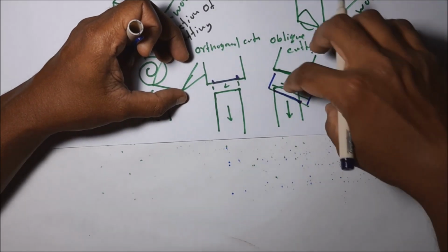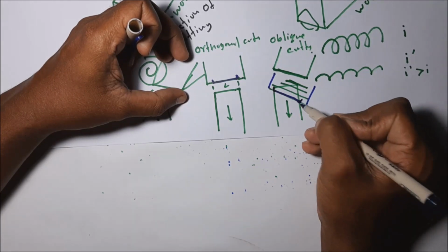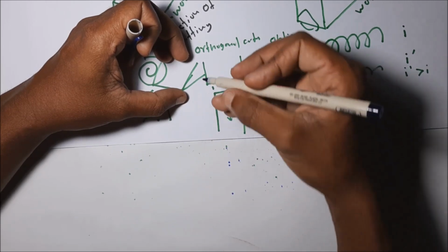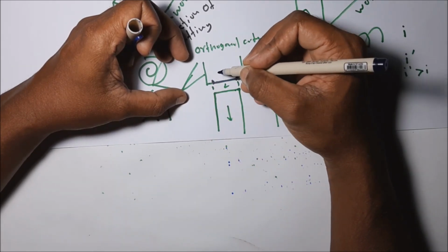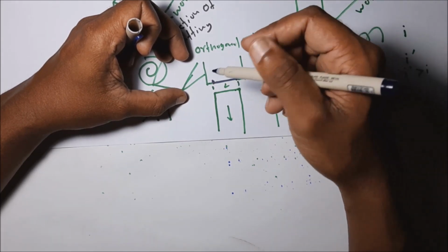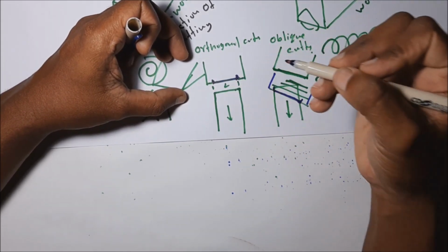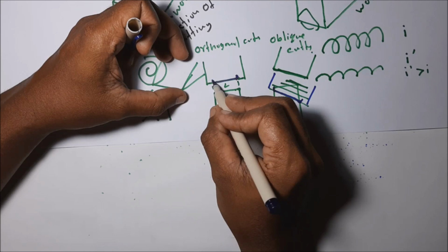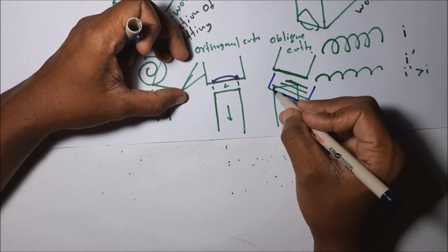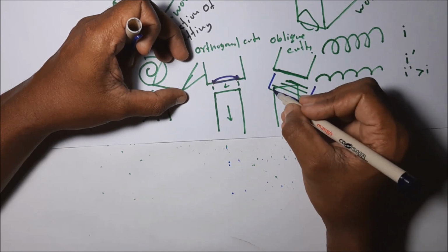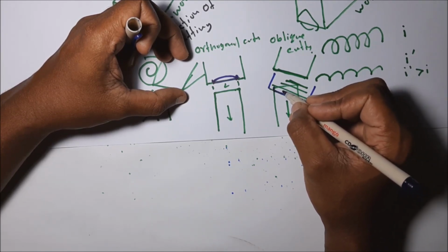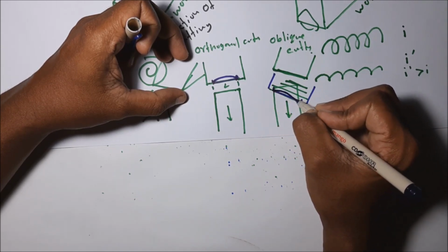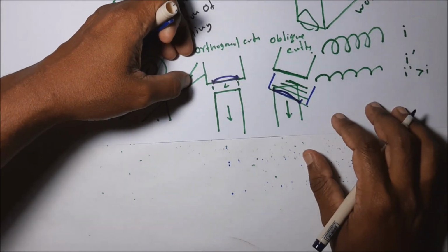So here, all the forces and all the heat generation are limited to a small area, which causes that small area to wear out immediately. But when distributed over a longer length, the pressure acting on the cutting tool is reduced and the thermal distribution is higher, so it has lesser tool wear compared to orthogonal cutting operation.